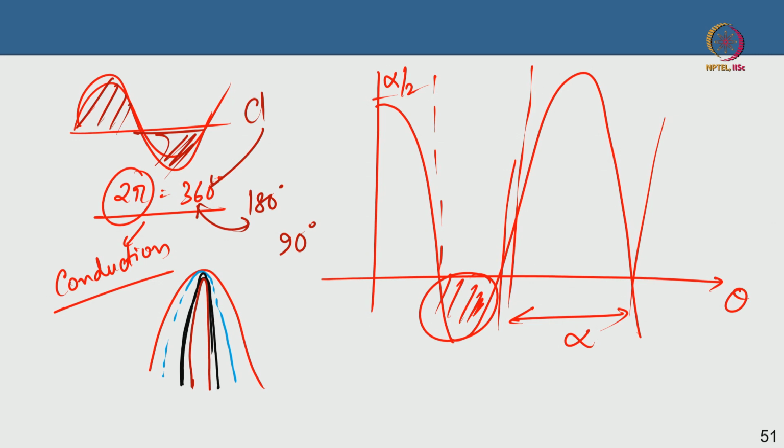When you bias below pinch off, you are going to clip the waveform, so that increases the non-linearity of the device, of the system, and it introduces higher order components. So you will get harmonics: second harmonic, third harmonic, etc. Those harmonic components can be exploited to your advantage. It increases the efficiency, your overall efficiency of the device will increase.